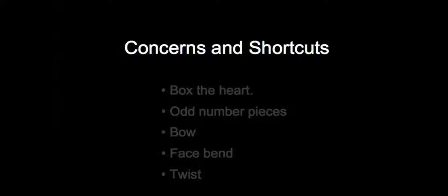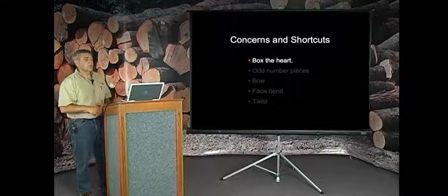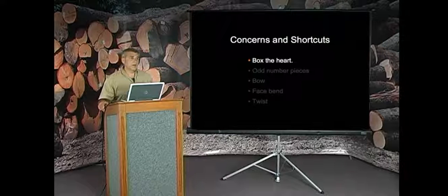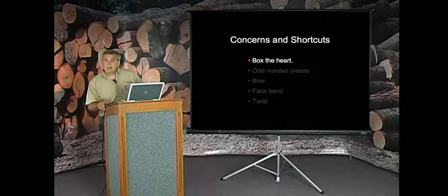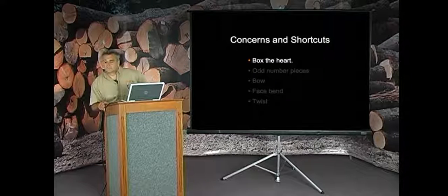There's several other characteristics of movement and issues that you have to deal with in lumber that are cause for concern. One of the things I've already mentioned, and that's boxing the heart. I think this is very, very important to cutting quality, good, usable, dimensional lumber. Doing it wrong, I have an ever-present example in front of me every time I walk down to the basement of my own home. My 2x10s that were floor joists, many of those, I did not box the heart, I split the heart. Well, not a lot of them, a few of them.